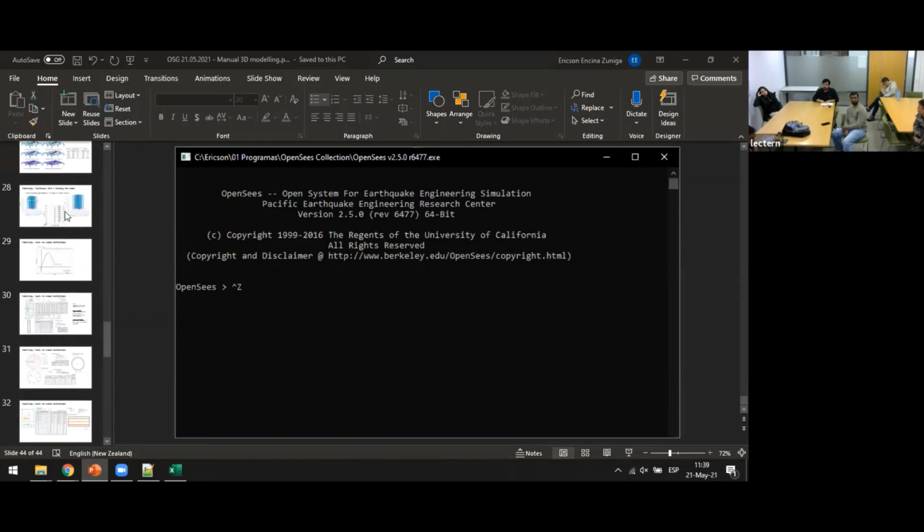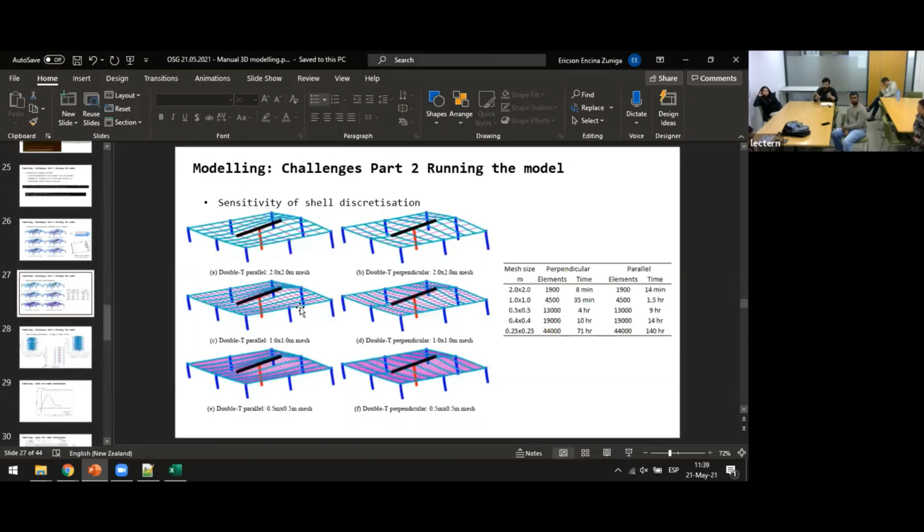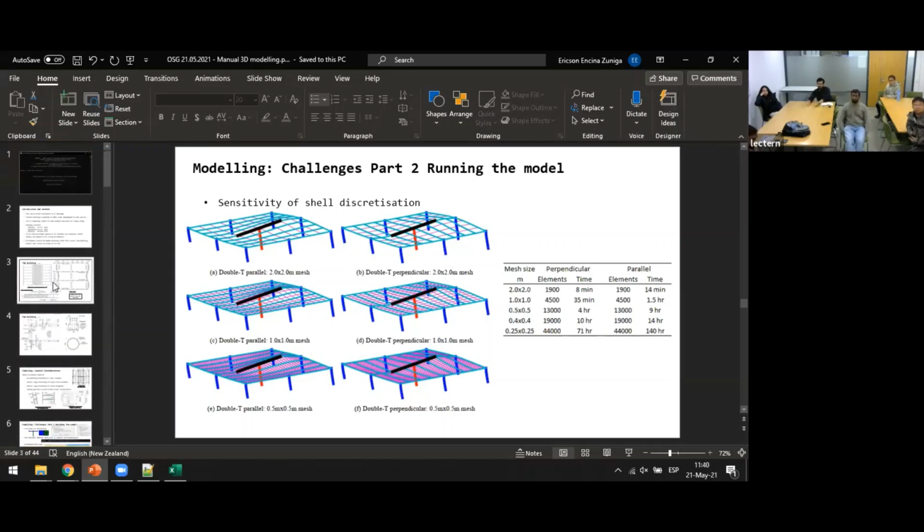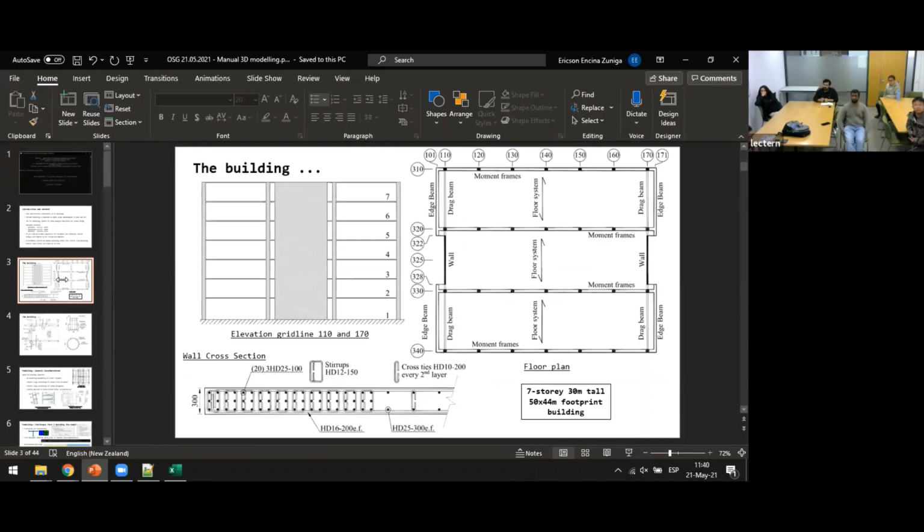Going around the connection of the floors to whatever support system, whether it's a core interaction with the lateral force resisting systems, whether it's a frame or shear wall, you assume it's more or less pinned, right? Yes, the web of the double T. And that's the supporting point, right? Yes. Did you consider any spring for the contribution of the floors in a perpendicular direction? For example, if you have the floors spanning this way, and you have frames perpendicular to it, how are they contributing to the rotations of the frame?